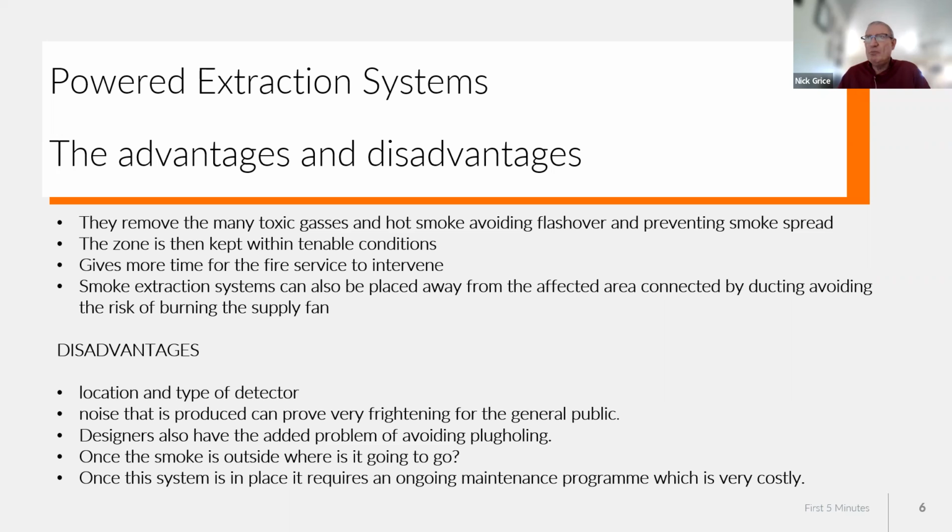It gives more time for the fire service to intervene, and they can be placed away from where the fire could be. So it could be like 50 meters away, connected by ducting, which then stops any wires melting or the burning of the supply fans.